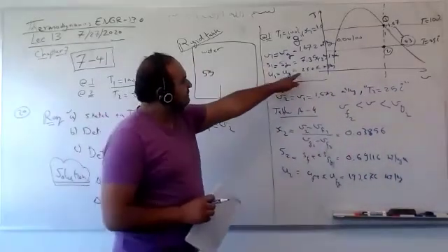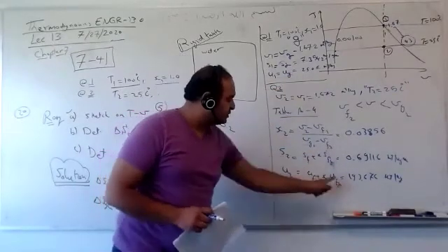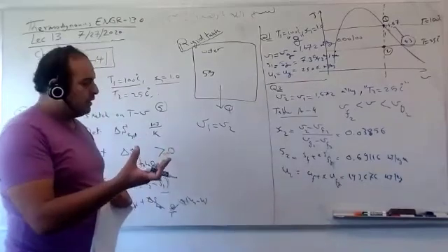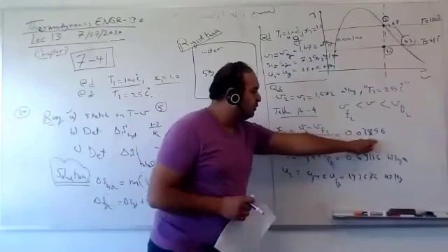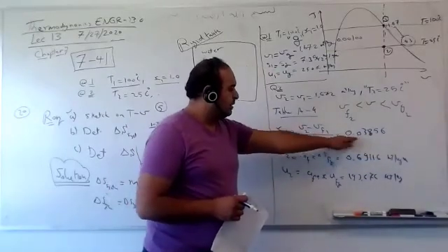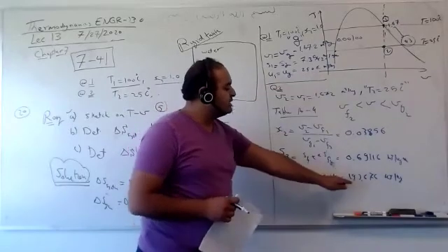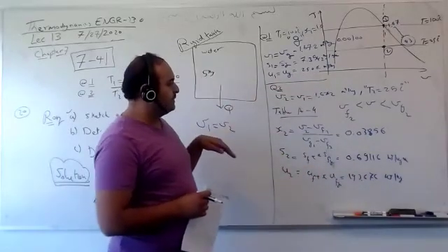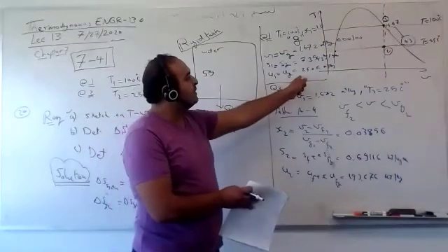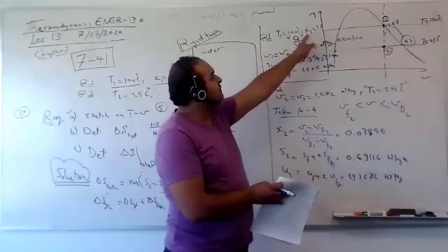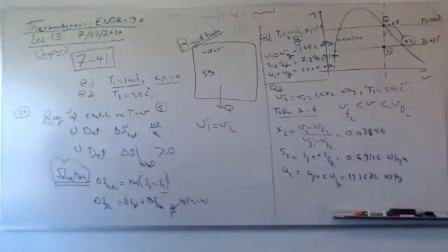So it was 2,500 became almost 200. 2,000, almost 1/10 of energy. So when you have water, energy 200, 300, it's almost pure water, there is almost no vapor. But this one, 200, this is 2,500. So energy decreases a lot because you cool down the system. Water in the liquid phase has a much lower energy than vapor. This is complete saturated vapor, X equal 1. Okay, guys, make sense?